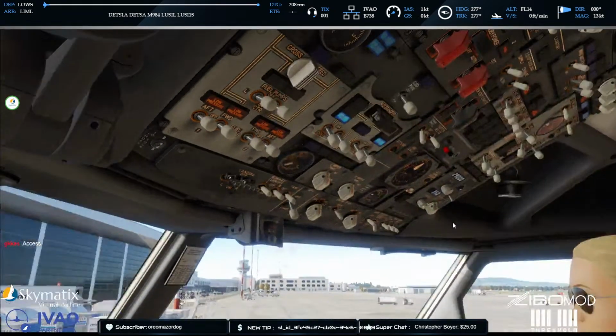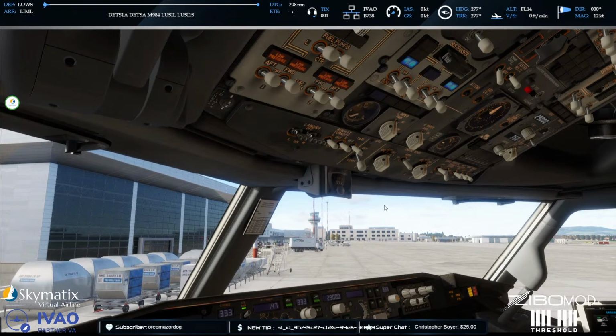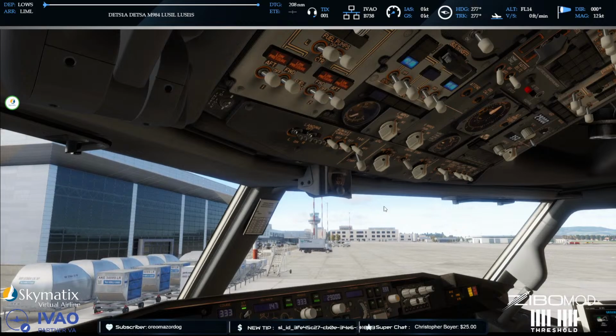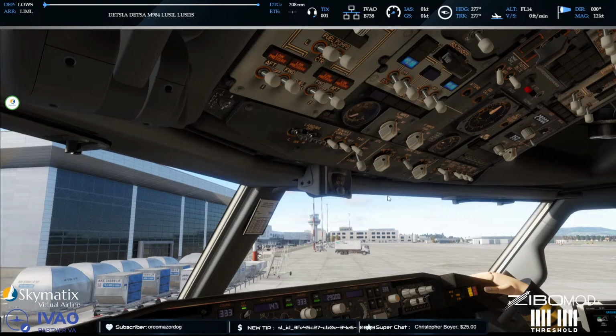The only thing is, maintenance-wise and cost-wise, it's cheaper to get to one of these forward pumps than it is to get to any of the other pumps. I think it's this one that they use. I can't even remember. But it's cheaper in labor, and the thing lasts longer. Depending on the airline you fly for, the guys will have different SOPs. But the fact remains, the APU has got its own built-in pump. In fact, I can start the engines without these as well because they're gravity fed. You just can't go and fly with them if they're off.